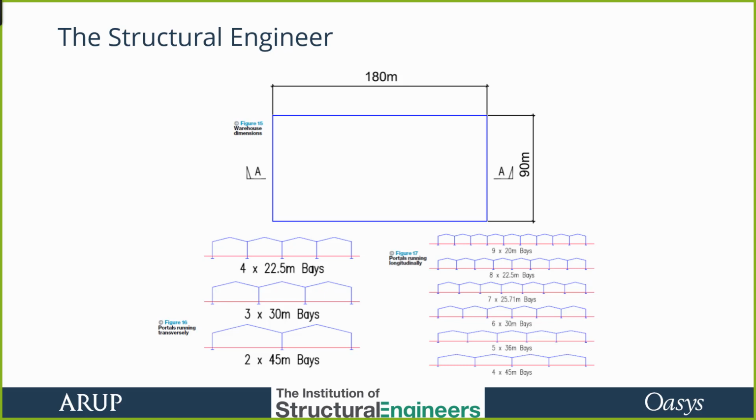If we put moment bases in, that will reduce the steel frame section sizes and weights, but that will require bigger foundations. And we're dealing with contaminated ground. Is that going to be a problem? And you look at all these options, and we've already got over 100 different layout options to choose from, even from just a simple portal frame shed.